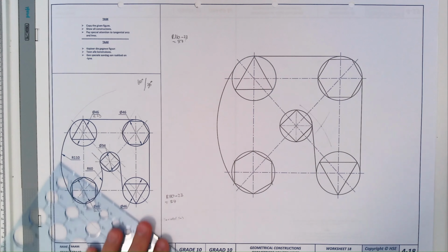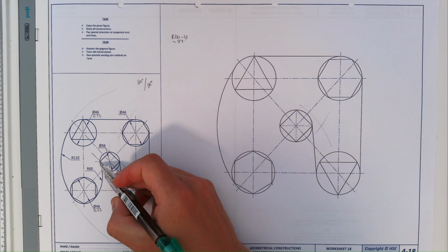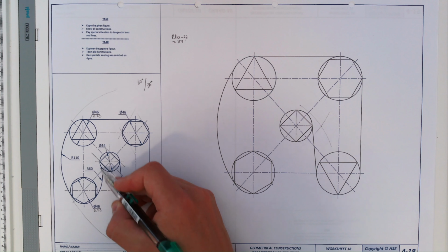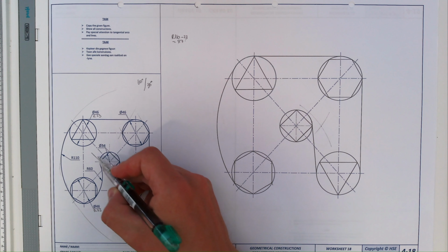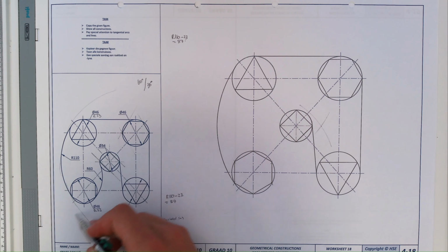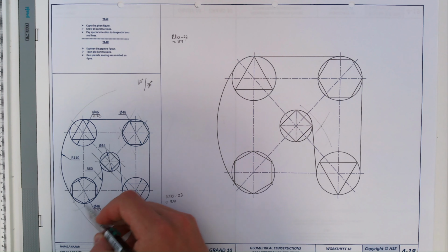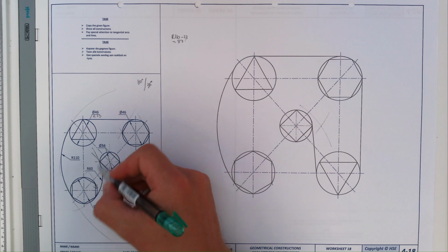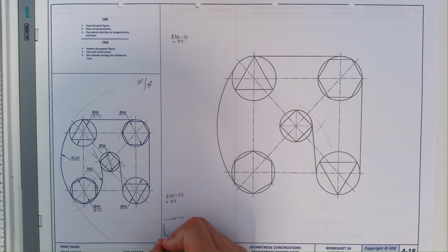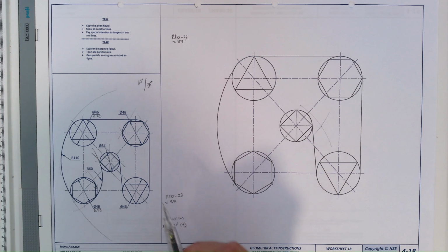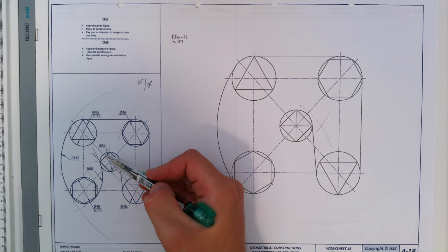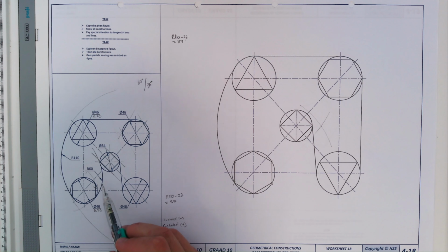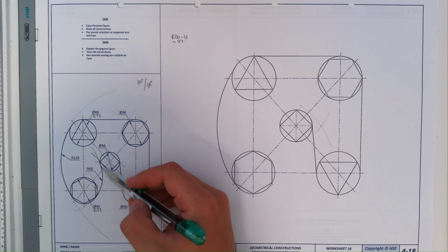Now this is an interesting one. If we look at this arc, that circle is included and this circle is not included. So this one is excluded, but this one is included. How do I know this? Because if I continue with this arc, you can see that this circle is on the inside of the arc, it's included, and this one is excluded. Excluded is plus. So we're going to take that radius plus this one's radius, and we are going to take this radius minus this radius, because this one is included and that one is excluded.